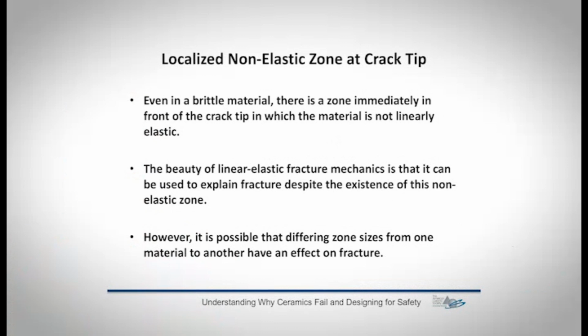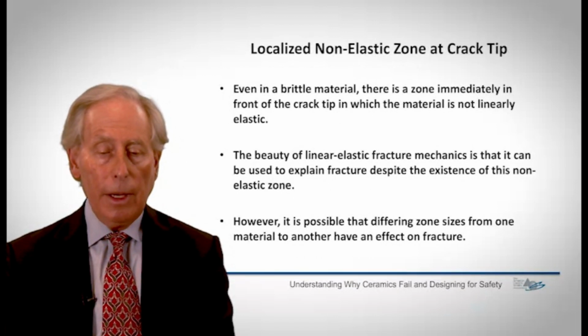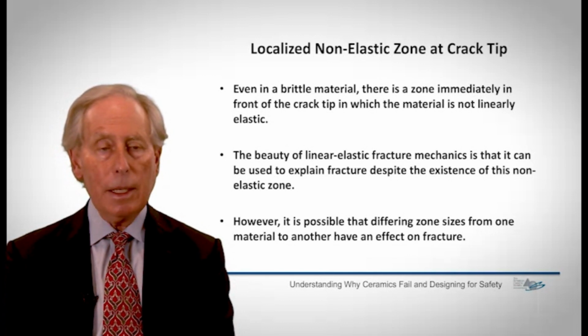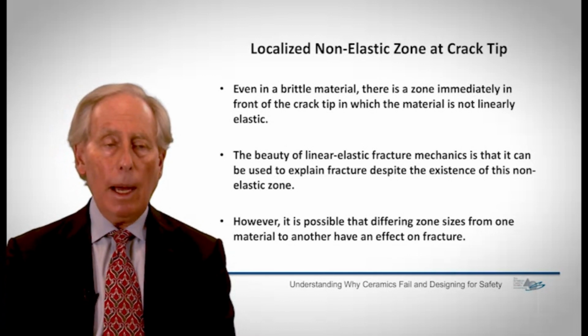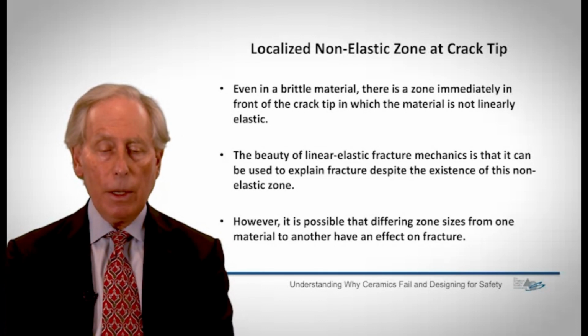However, one of the things I should say is that we say that brittle materials have no plastic flow, no dislocations at a crack tip. But the fact is that very near a crack tip, there is a nonlinear elastic zone. We don't really know how large it is. It can be a few atoms in extent, but the elastic modulus is not completely equivalent to Young's modulus all the way into the crack tip. So there's a non-elastic zone, if you will, right near the crack tip.